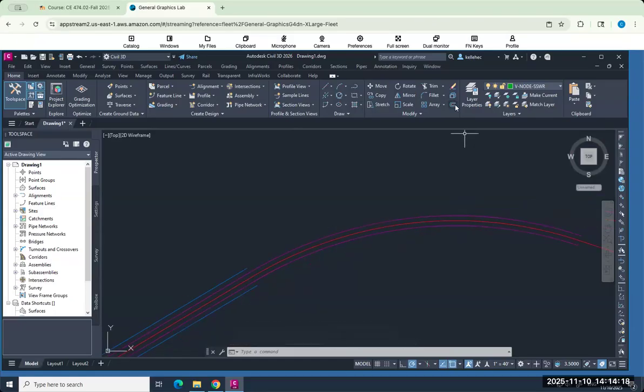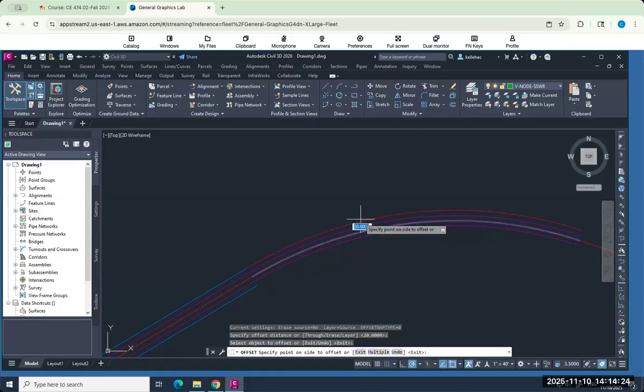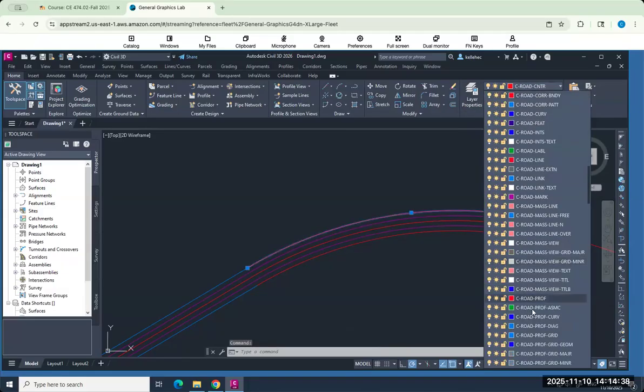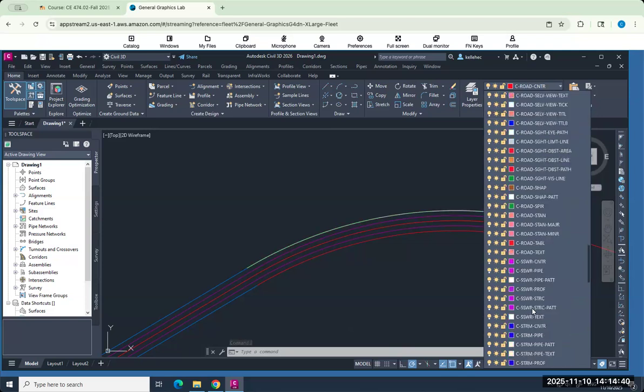Again, you would initially offset this, right? Offset distance of 20. I'm going to use these. My encouragement, still, these will be P-lines the way that we've drawn them, is that you can duplicate these, you can copy them, and this will be the edge of your lot over here.